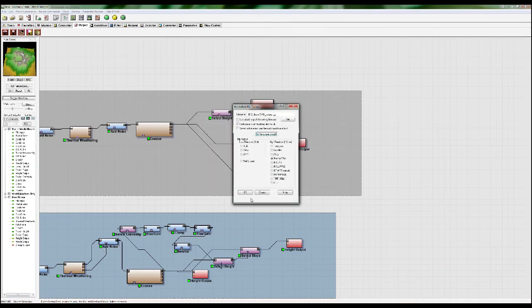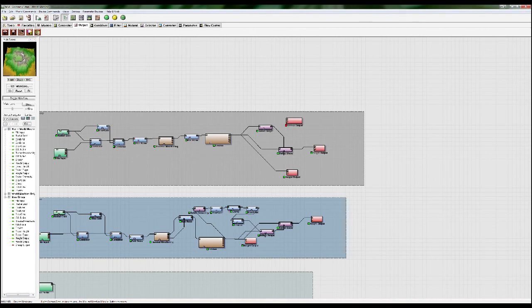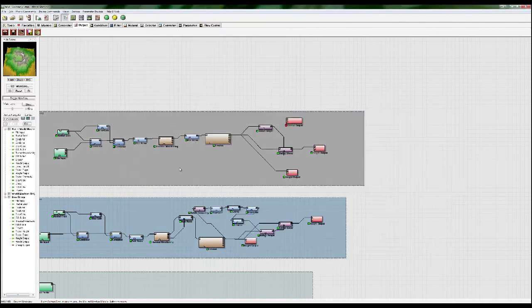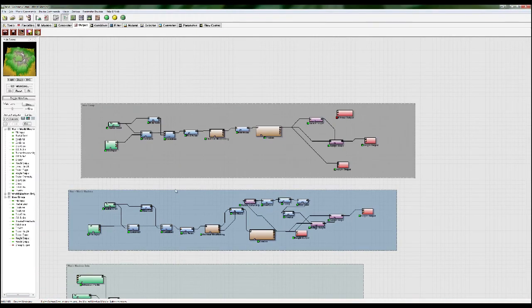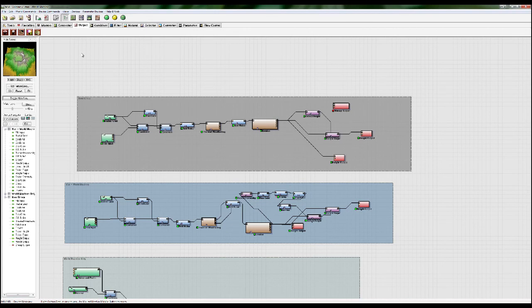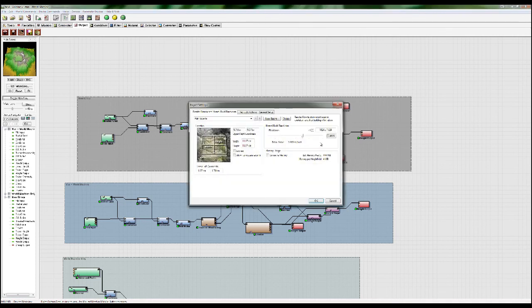It'll have to build the terrain. So at this point you don't want to end up with a terrain this big. You want a terrain that's your 4K, as high resolution as you can, as your machine can deal with. So some people will be 2K, some 1K. It really also depends on the distance away from the camera, but Vue tends to handle the high res assets pretty well. So if you want to change your resolution and you don't know how, up the top left, click on this, you've got your resolution there. You want to untick the +1 as well. That's for programs that use a +1 on their resolution, like Erosion. We don't need that.